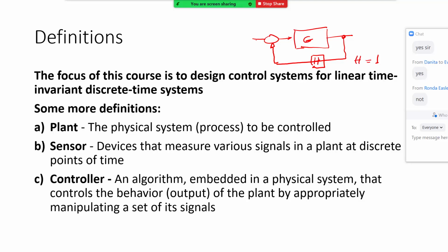It means two things. It means, of course, it's a scalar value, but that doesn't matter because I can always rewrite this feedback loop and make it a 1. The scaling is not what I'm talking about here. So this 1 could have been 5 or 10 or 100 or 0.01. That doesn't matter because I can move it around to make it a 1. But the more important point is that this H usually is very fast, and therefore there's no dynamics in it.